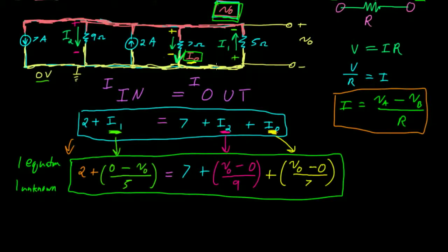So over the past few videos, we've taken this circuit and we've written our nodal analysis equation, and this is a circuit which has two nodes. So we always write an equation for all of the nodes in a circuit that are not the ground node. So I've only got one equation here because I've got two nodes, so 2 minus 1 is equal to one equation. And I wrote the equation, current in to our node V0 is equal to the current that flows out